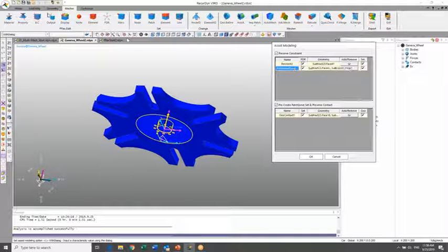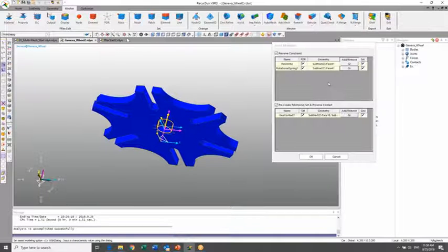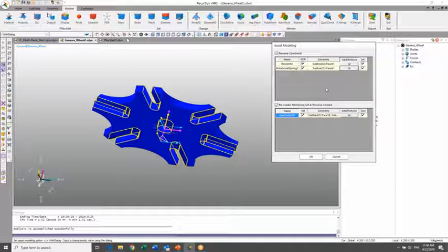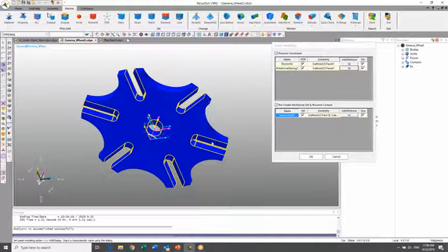And so it did the same thing with this rotational spring, that spring damper. So I'm going to go ahead and select that again. And for the contact, in order to preserve the contact, it needs to make a patch set. That's one of the things that you can do manually. It needs to make a patch set where the contact's going to be. And you can see where the contact was already defined with all of these regions where that pin can come in contact. And I'm going to go ahead and leave that as is.